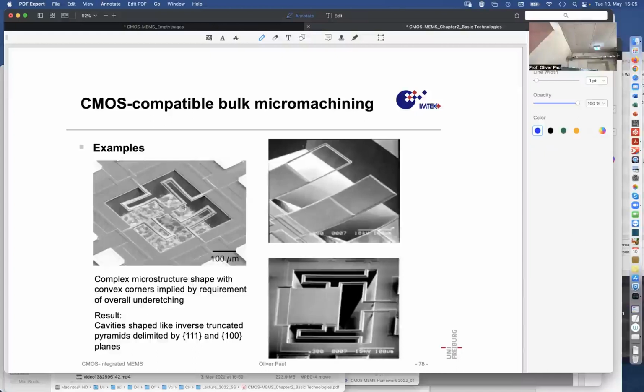I'm not sure you have heard that name. Van der Pauw is a guy who showed how to measure the sheet resistance of materials shaped arbitrarily with 4 contacts at their boundary, actually 4-point contacts. And the realization to approximate such point contacts is to make crosses with extended contacts that act as if they were point contacts, because they're far enough away from where the real action happens in the center.